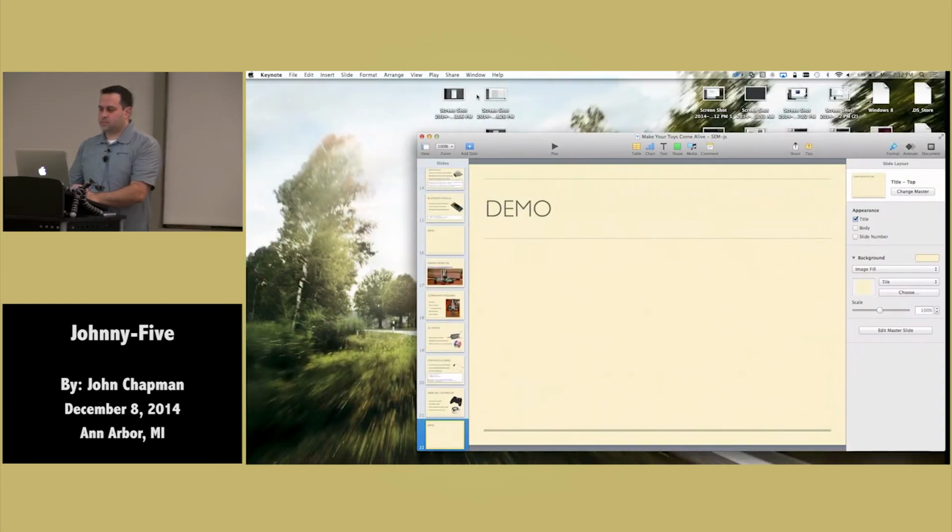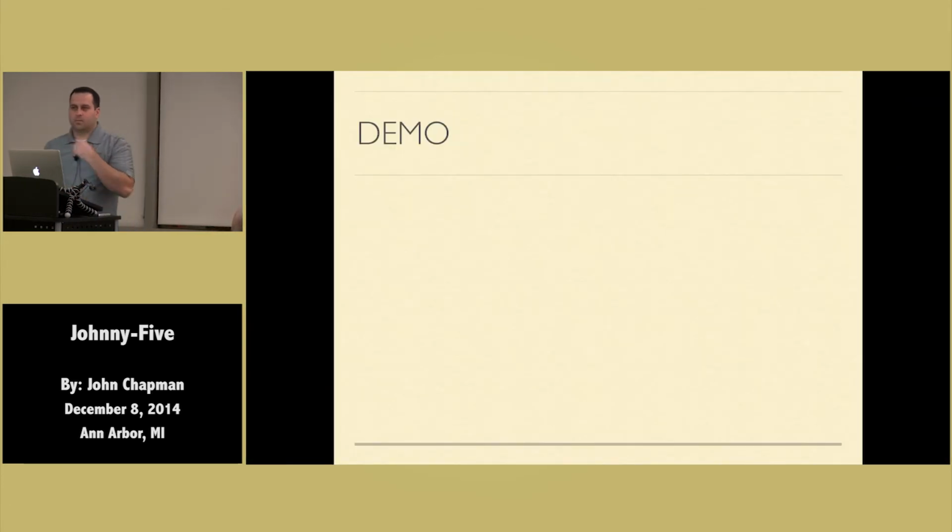Yes? And if you wanted to eliminate the Mac from that loop, you would use one of those all-in-one solutions we were talking about earlier. Yeah, so you have multiple options. The Galileo is a great option. One thing that I don't like about the Galileo is this Arduino that I'm using has a built-in linear voltage regulator, right? So all the logic that has to run on Arduinos and most of this hardware has to be at 5 volts.